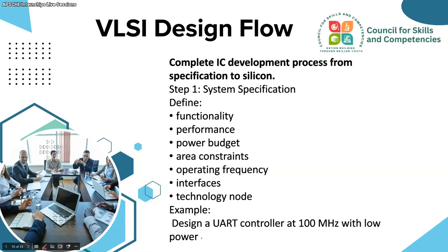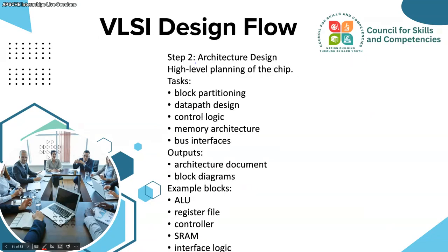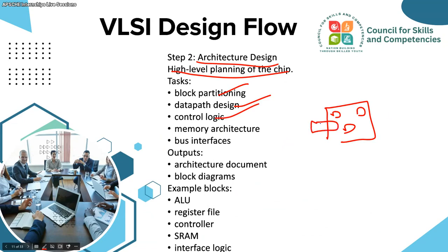Next is architectural design. It is high-level planning of the chip. For this UART, what blocks do we have to keep, what registers do we have to get, what is the data path, what is its control logic. You will have control registers for this. And if it has memory, how is it going to be accessed, what are the bus interfaces. Those things are decided at the architecture level.